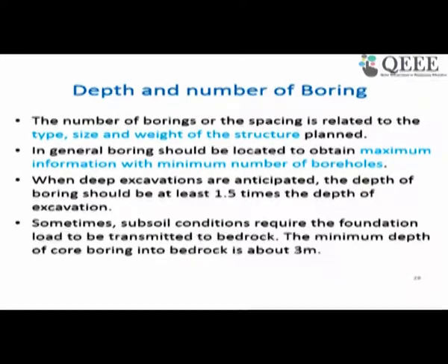Now, this number and the depth will depend on the type, size, and weight of the structures, and our objective is always to get maximum information from the site with the minimum number of boreholes. As you know, drilling operation is a little costly, so more boreholes will add to the cost. So you try to minimize the number of boreholes, but without compromising the information.